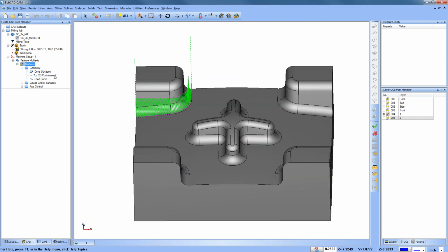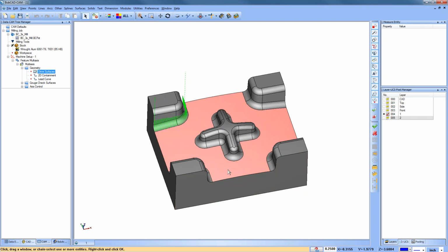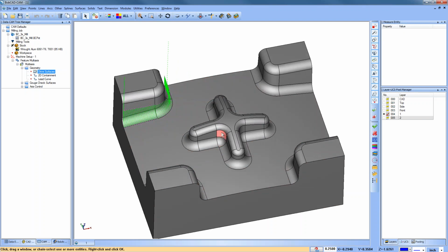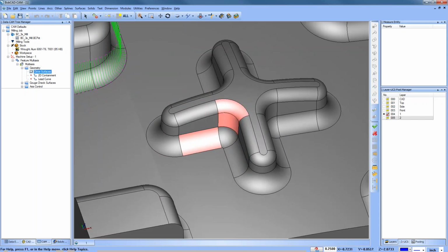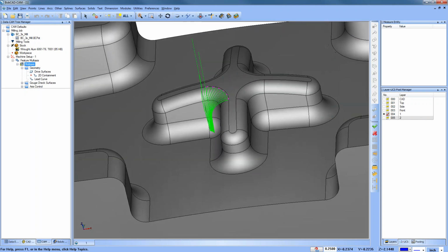It could be anywhere on your model. What's important to understand is that the toolpath you generate is going to be perpendicular to that curve. So if I do another section here, say these two sections, and then pick this curve right there, I can compute, and you can see the toolpath that we get to cut along in that area.